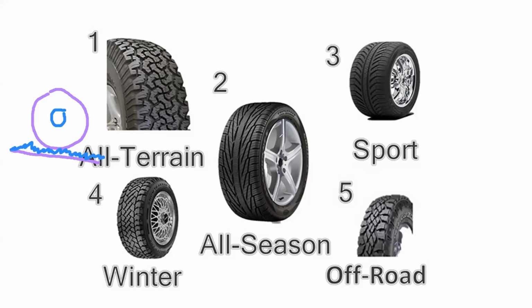But even the threads have a maximum limit on the water they can take. For these wheels at a particular speed, the maximum is around 30 to 80 liters per minute for a certain amount of RPM. If the rainfall is higher than that, you will again have aquaplaning, because the tires cannot withstand that much water.